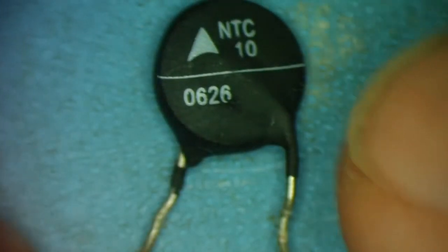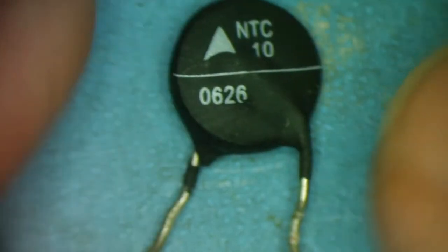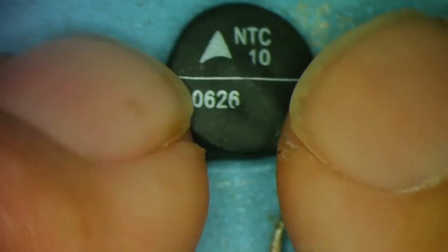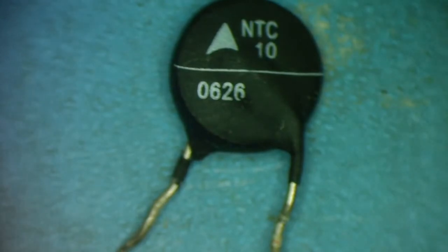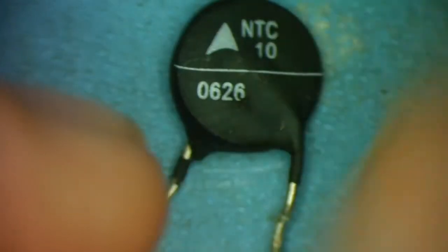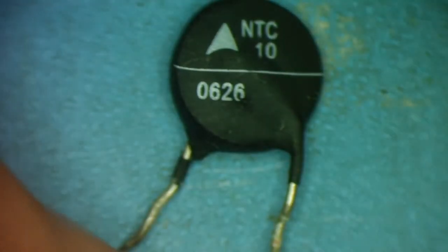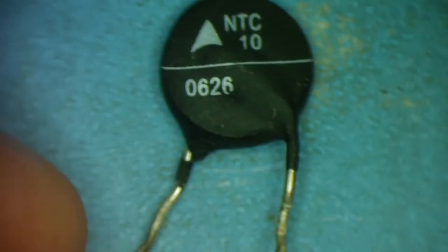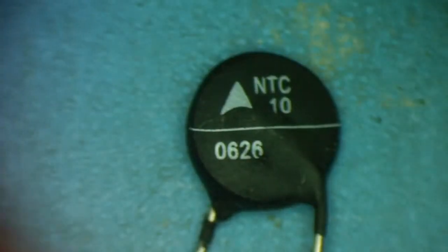They start off as maybe 3 ohms. The current starts to rush in, charging the capacitors, and as it does so, it warms the resistor inside, and the resistance drops. So after a few seconds, it drops to like 0 near enough, and the thing effectively isn't there as far as the circuit's concerned. So those are thermistors, yeah.